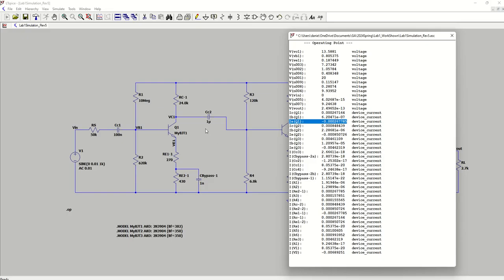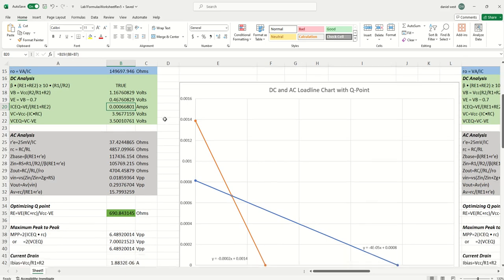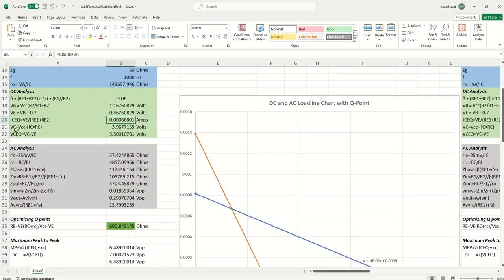So you can see that just a tiny change through the voltage at the base makes quite a big difference, whether it's going into cutoff mode or saturation or staying in the quiescent point. So looking at my voltage through the collector for the theoretical, I'm around 4 volts.